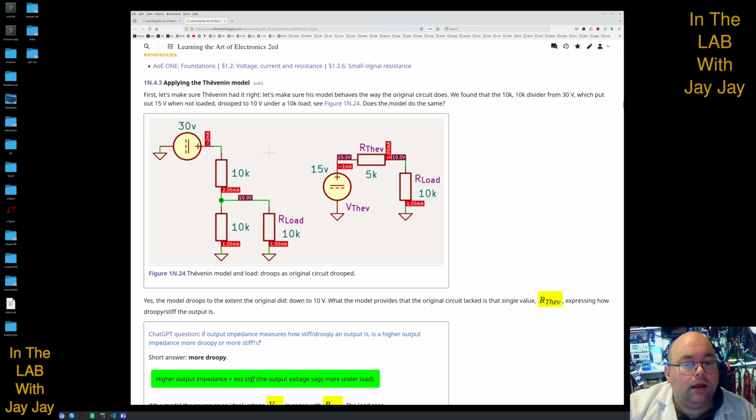So we want to find that the 10K 10K divider, when given 30 volts, put out 15 volts when not loaded, and drooped to 10 volts under a 10K load. See figure 1N24. Does the model do the same? So that's what we want to just see.